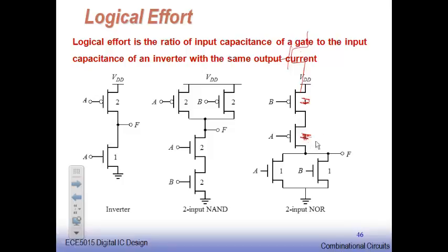So you will have what? And I will have another input for C. And this input will be C with the PMOS here. So the size would be what? 6, 6, 6. Therefore for 1 input, 7 by 3. Whereas 5 by 3 it was for NAND gate. This is another way how you can explain why NAND gates are preferred over NOR gates.